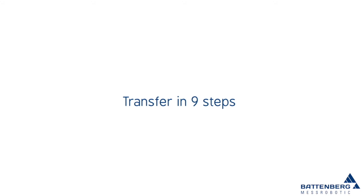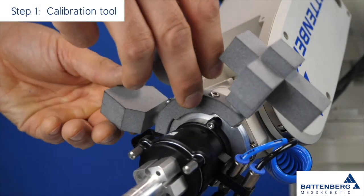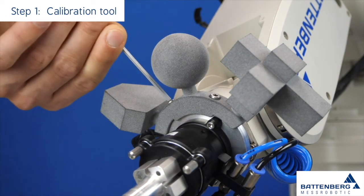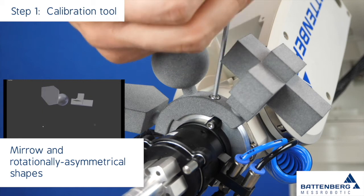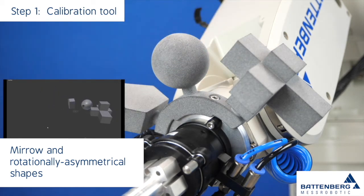The transfer process takes place in 9 steps. 1. Attach the calibration tool to the robot arm. The Battenberg reference tool can only be attached to the robot arm in one clear way. The rotationally and mirror symmetrical shapes are easy to fit and allow the exact position of the robot arm to be determined. Therefore, the reference body serves as the origin of the transformation chain.